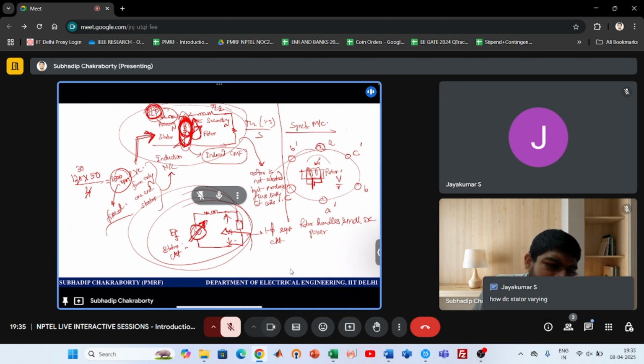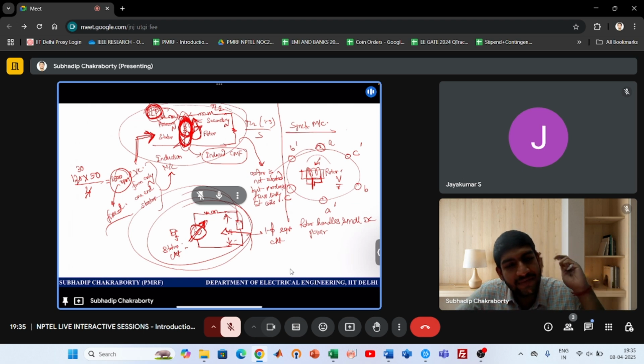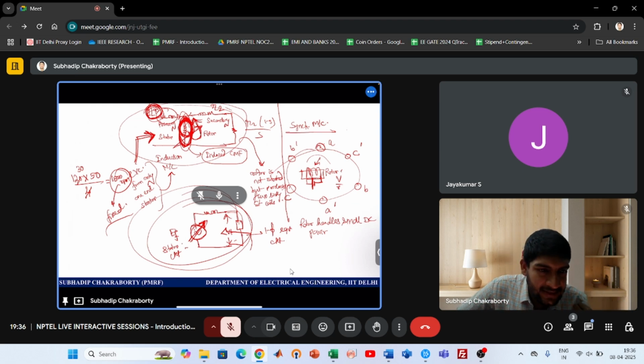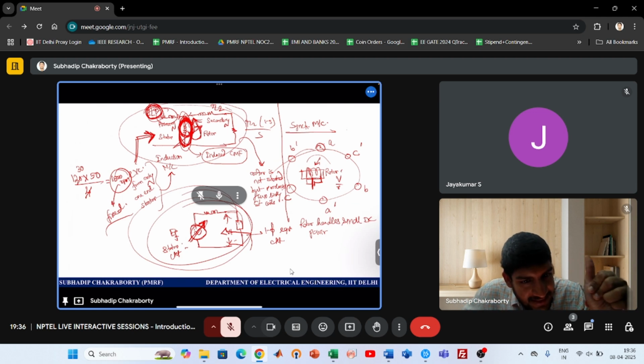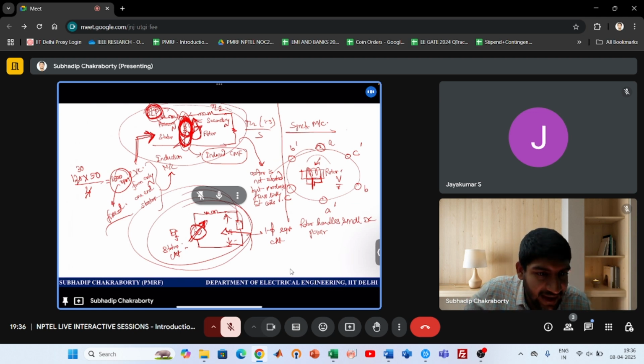No, stator not DC. Stator is AC, right? See, simply if you give some DC battery and supply the rotor, it will lead to DC currents. But those currents will produce flux, like the rotor flux or the field flux in a synchronous machine, cutting the conductors of the synchronous machine. So what does a rotating magnet do, what form of voltages does it create in the stator?